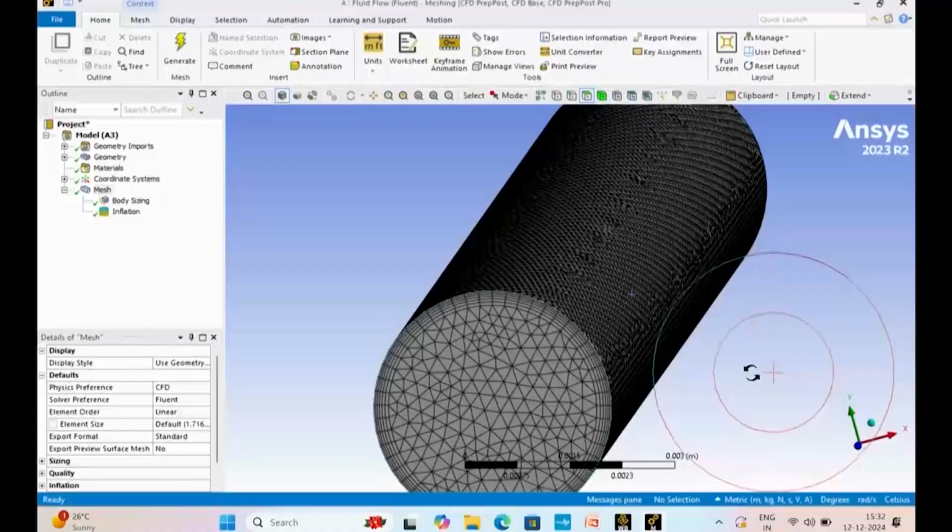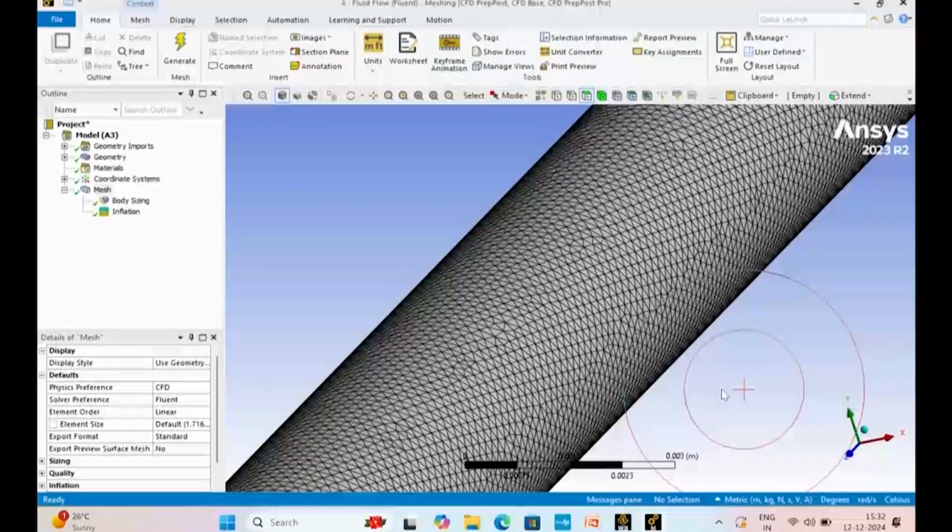Very interesting. Did you observe that the surface mesh was a rectangular mesh before, I mean hexa mesh. Now it changed. Just see the surface. Yes, the surface mesh already changed. So that is the problem here. It is very hard to control which mesh you want. That's why now you see Ansys Discovery. It's a very nice one.